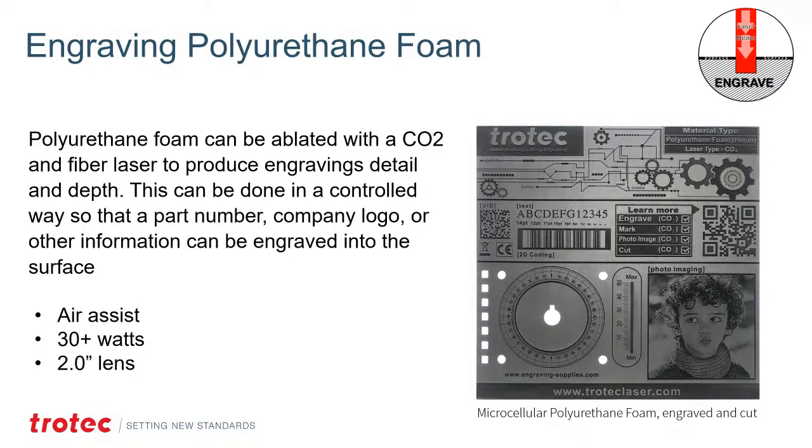Just so you know, the polyurethane foam works with air assist. I do recommend air assist if you're cutting it, 30 plus watts for engraving it, and just a standard 2-inch lens. So that is the process of working with this.